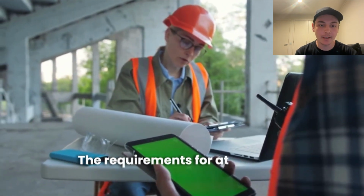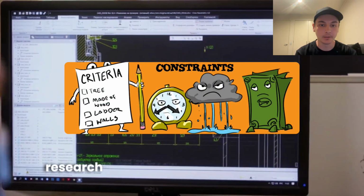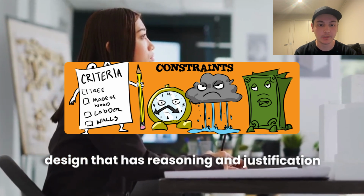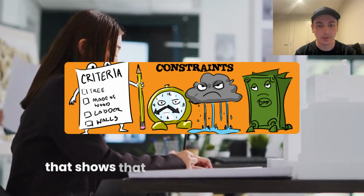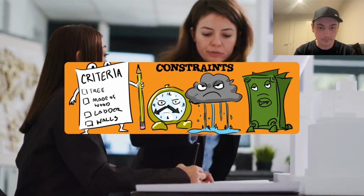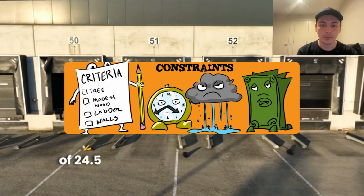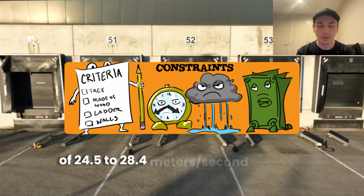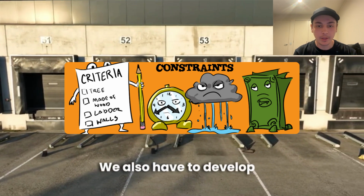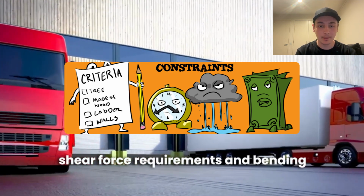The requirements for AT4 that stakeholders would like to see are highly relevant and accurate research and optimization in order to see a design that has reasoning and justification, and evidence that shows that the design will comply and, most importantly, be safe for others. For this task, we must stay within the gale force of 24.5 to 28.4 meters per second from the Beaufort scale. We also have to develop a set of requirements for axial deflection, shear force requirements, and bending requirements.